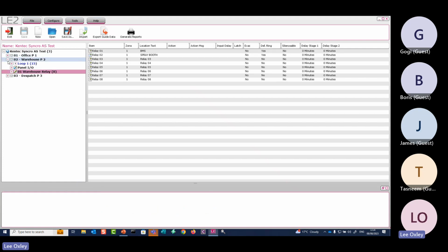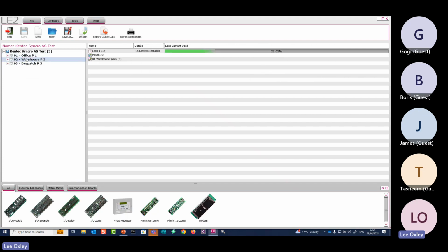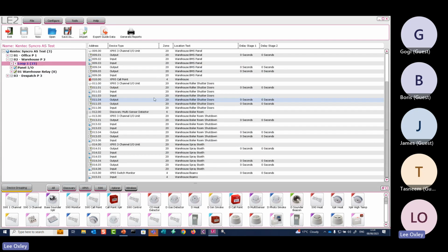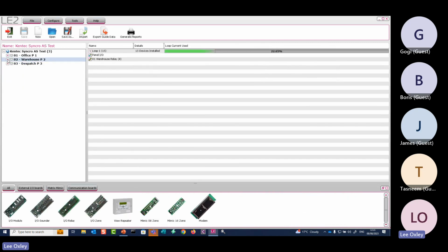All I need to do now is connect to panel 2 with a contact lead and upload this configuration back to the panel. So it'll take everything it had before, plus any additions I've physically fitted out on site as well. Okay, and some alterations to those additions as well. So like I say, you must auto-learn the panel.